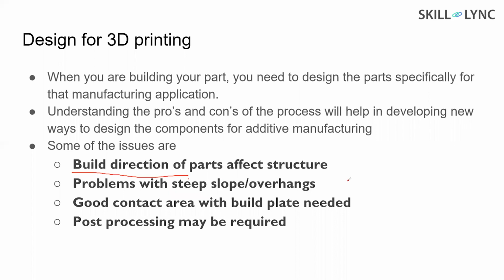And the contact area. I told you about the build plate. When you are putting some object on top of your build plate, you need to make sure that the whole surface is touching your build plate, so that this surface will stick or adhere to it. When it sticks, it will be stable against vibrations or any disturbance happening in your machine. Your model should withstand all those things, so it should have a good contact area.